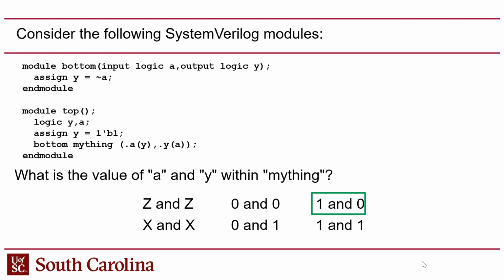So Verilog has 1 and 0, but it also has Z, high impedance, meaning the signal's not connected to anything, no one's driving it, and X. The problem is X, because X can mean a lot of things. X could mean conflict, signals in conflict. It could mean the signal's undefined because it's coming out of a RAM or a register that hasn't been initialized. It could mean don't care. If you're setting a don't care in your design, you can set a signal to X, right? Well, that's terrible. Why not have separate values for that stuff, which VHDL does.